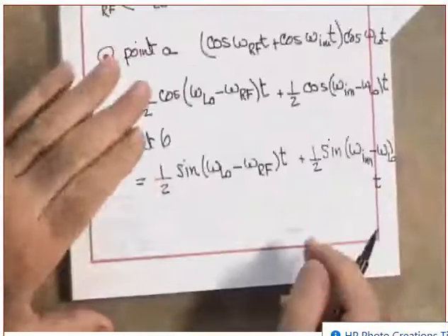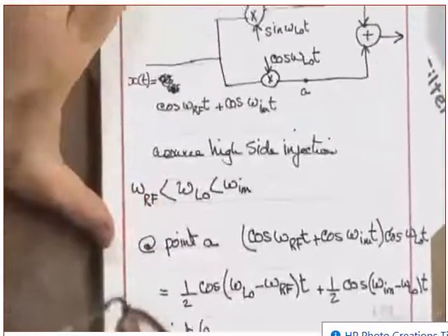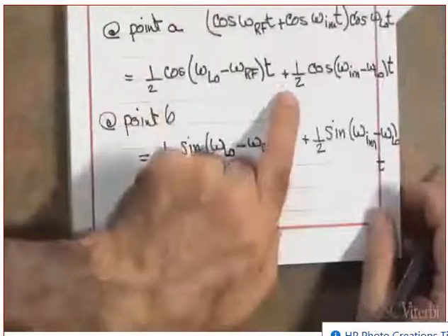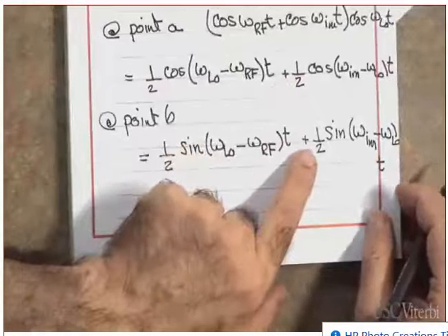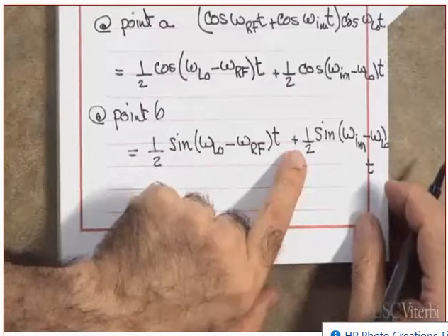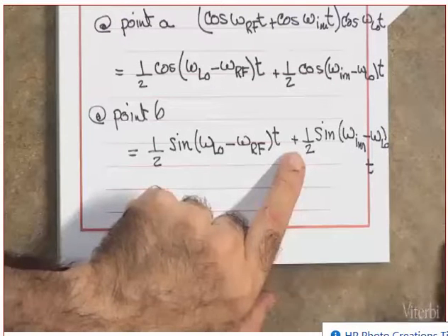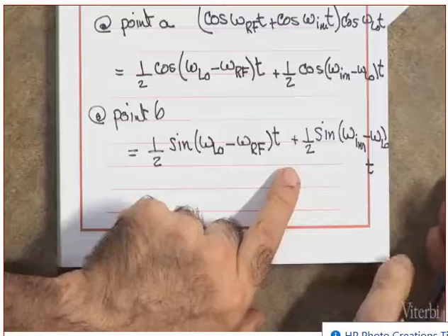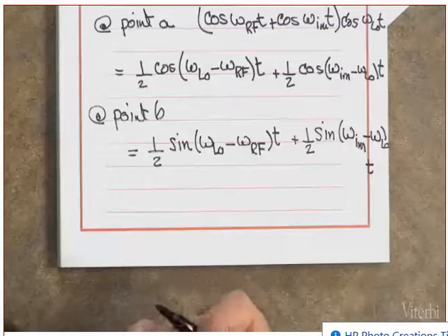You can do it with trigonometry. Yes. There is an addition in the second term of the sine. Where? At the bottom of the page. This one? The second term. Second term, there's an addition between the two frequencies, the value IM and the value LO. The two frequencies are added together. This one will be filtered out. Ah, sorry. The sum will be filtered out. You just keep the difference.